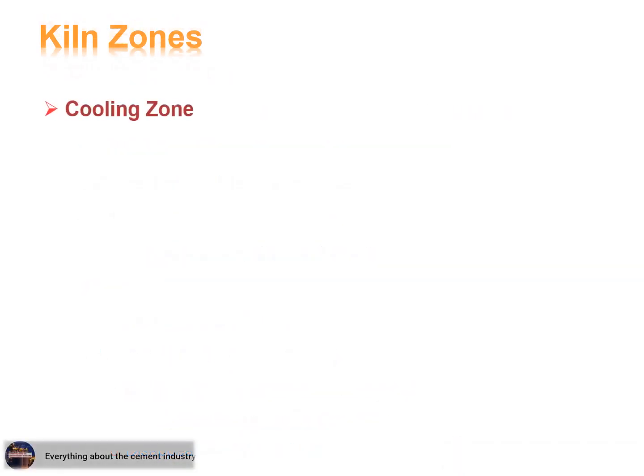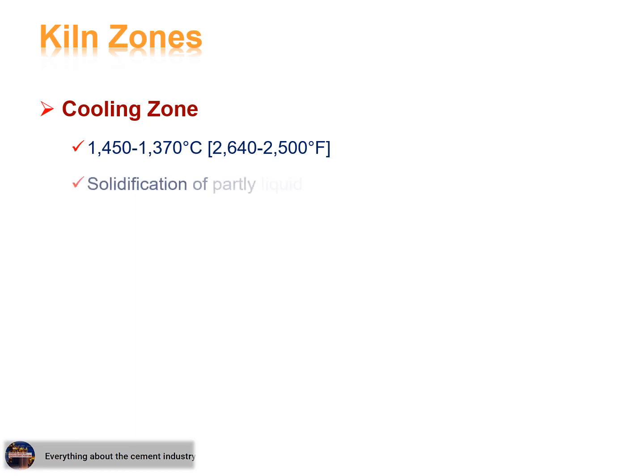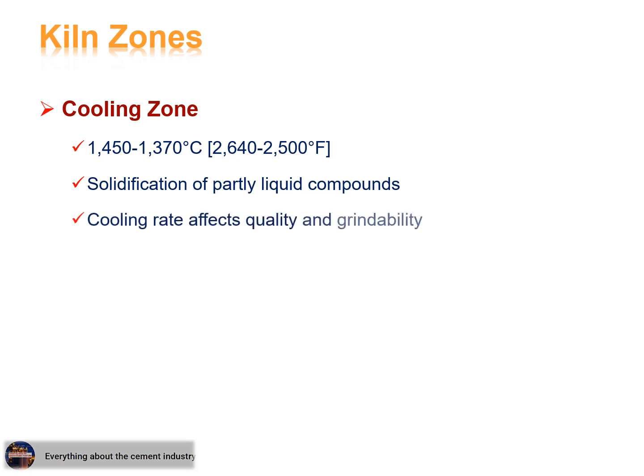Cooling zone. 1450 to 1370 degrees. Solidification of partly liquid compounds. Cooling rate affects quality and grindability. Alite crystal growth. Freezing of MgO.